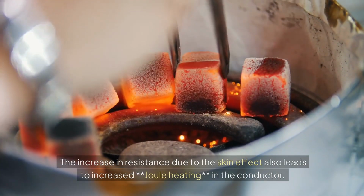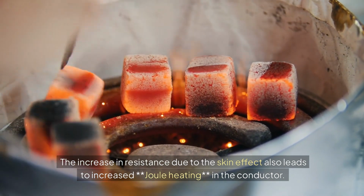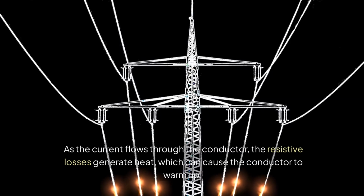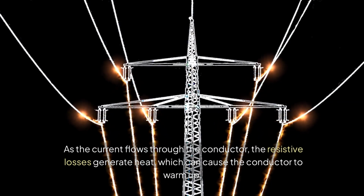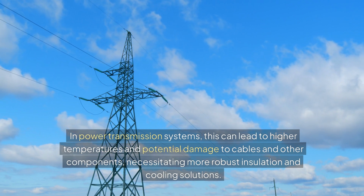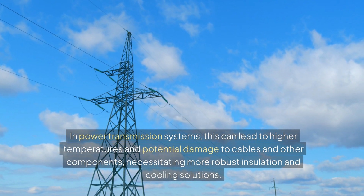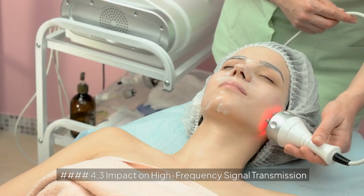Number 4.2 Heating. The increase in resistance due to the skin effect also leads to increased Joule heating in the conductor. As the current flows through the conductor, the resistive losses generate heat, which can cause the conductor to warm up. In power transmission systems, this can lead to higher temperatures and potential damage to cables and other components, necessitating more robust insulation and cooling solutions.